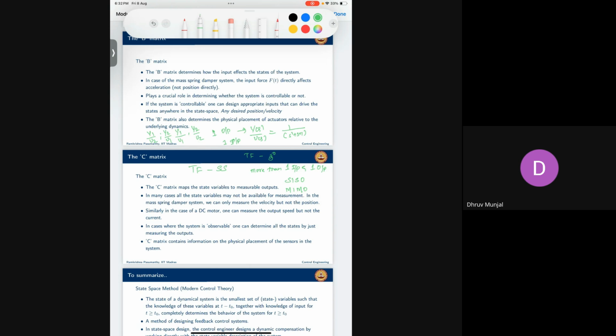It can be represented using a transfer function, but when it goes to more than two inputs and two outputs, it will be very difficult and tedious to calculate. So there comes the state space representation to the rescue. You can easily represent higher order systems in terms of matrices, with matrix properties, using the state space representation rather than the transfer function. So it's a more convenient representation.